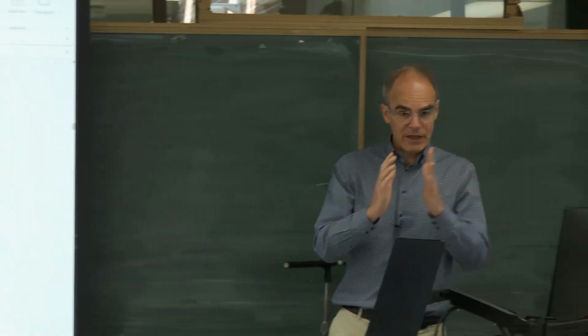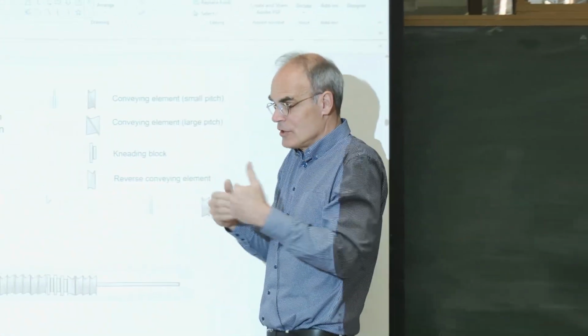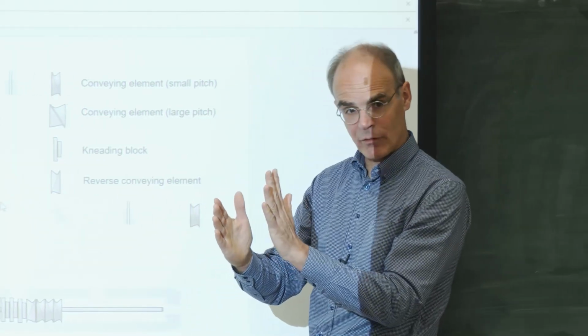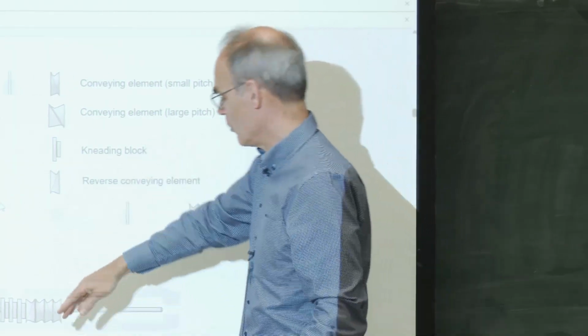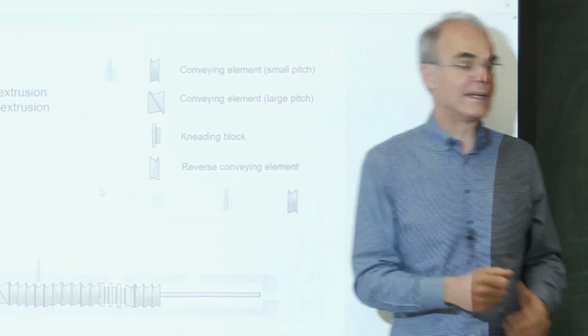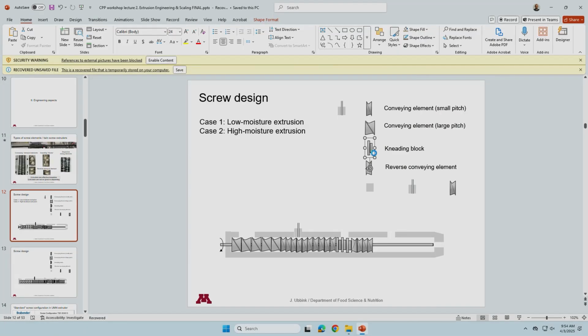So you have a kneading zone which can have a number of these blocks, but at some moment there's no active transport in there, and it's even sent back. So you just have a limited zone of them. Then typically you get into a transport zone again. You start kneading again. So typically you can say I want a second series of kneading blocks, so we can build them in here.